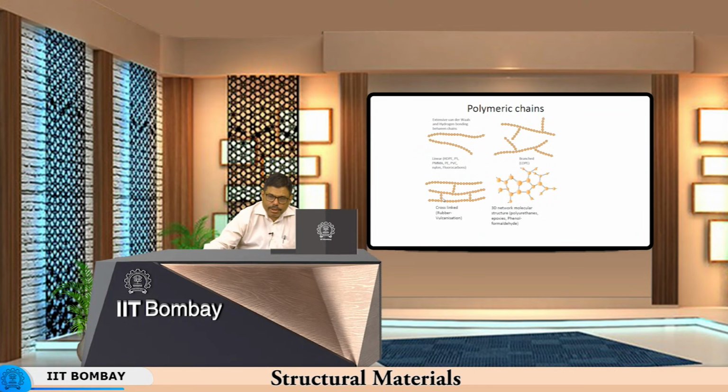Typically polyurethanes are used for tool materials with relatively low life, but these are modern tool materials which are relatively light. So if you want a lightweight tool, then you can make it from this particular material. So the strength is derived from extensive cross-linking.